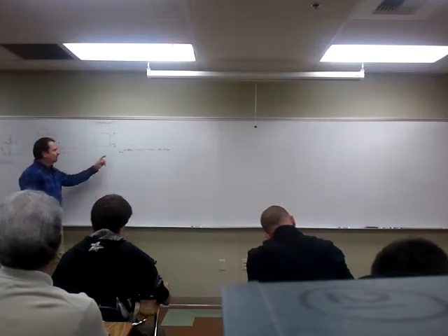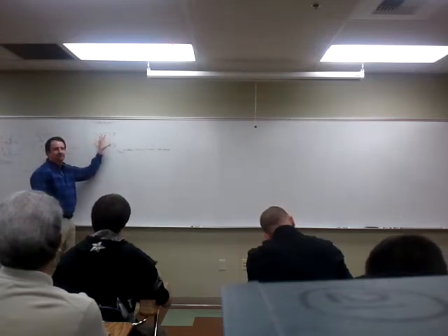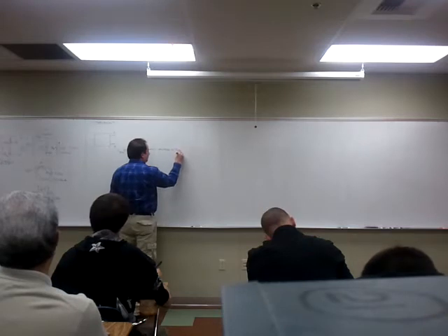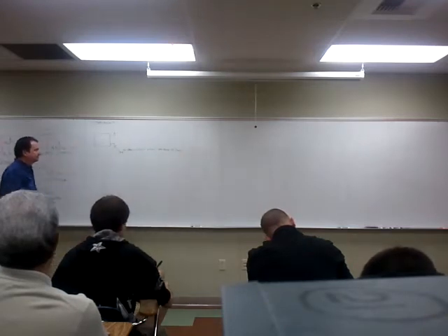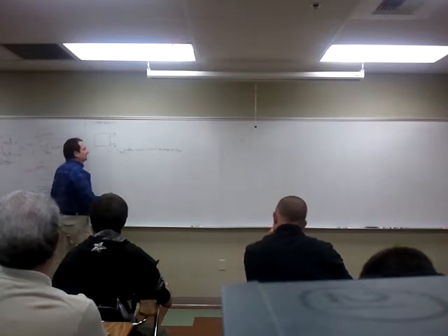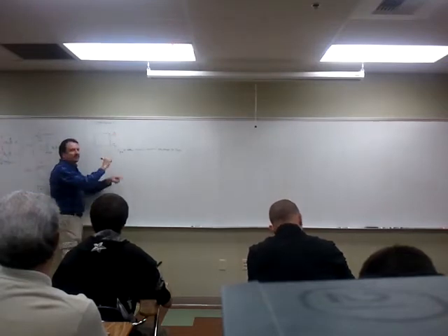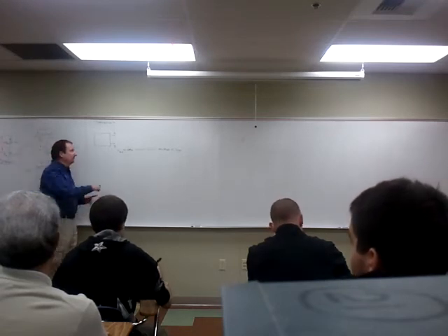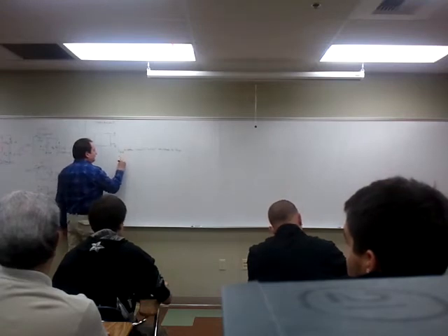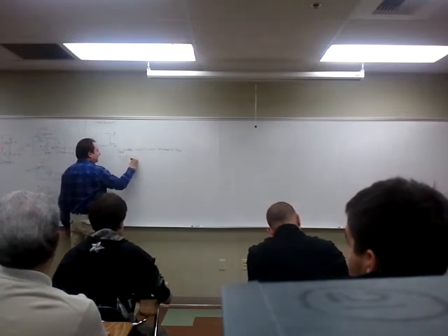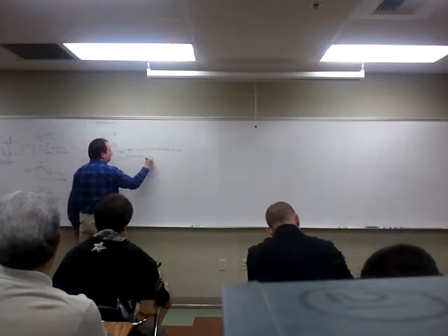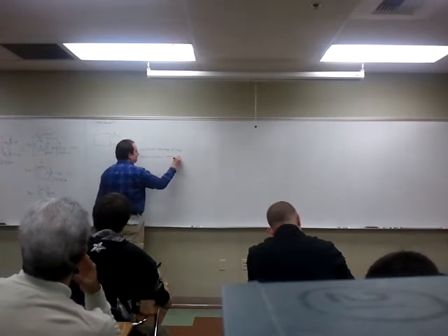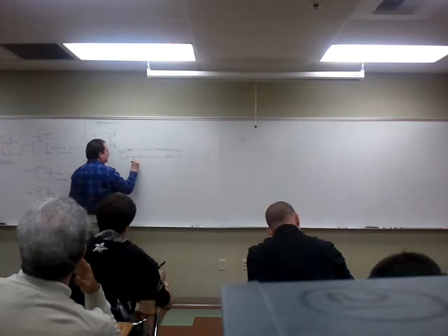By definition, any voltage that you measure between 2 points that you define, once you define the 2 points, the open circuit output voltage, we'll be calling V Thevenin. VTH stands for V Thevenin. What's another thing you can measure? I could put a voltmeter and measure the voltage coming out of this circuitry of this black box. I could get an ohm meter and measure the resistance from A to B. And that's the resistance looking back into terminals A and B.